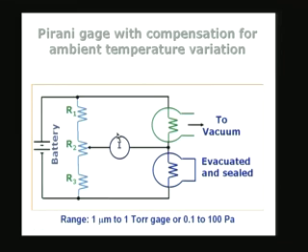So, let us see how it is going to operate. I have a source of power, and the source of power is going to send a current through the gauge here and also the compensating gauge. It is also going to send a current through R1, R2 and R3. R3 is a variable resistor. So what I do is I treat R1, this gauge, R3, and the compensating gauge as a Wheatstone bridge. You can see that this forms one arm of the bridge, and this forms the other arm of the bridge, and the other side is connected to the negative of the battery, and the battery is going to provide a source of power. It is going to heat the resistance here and also the resistance here by sending a current through the element.